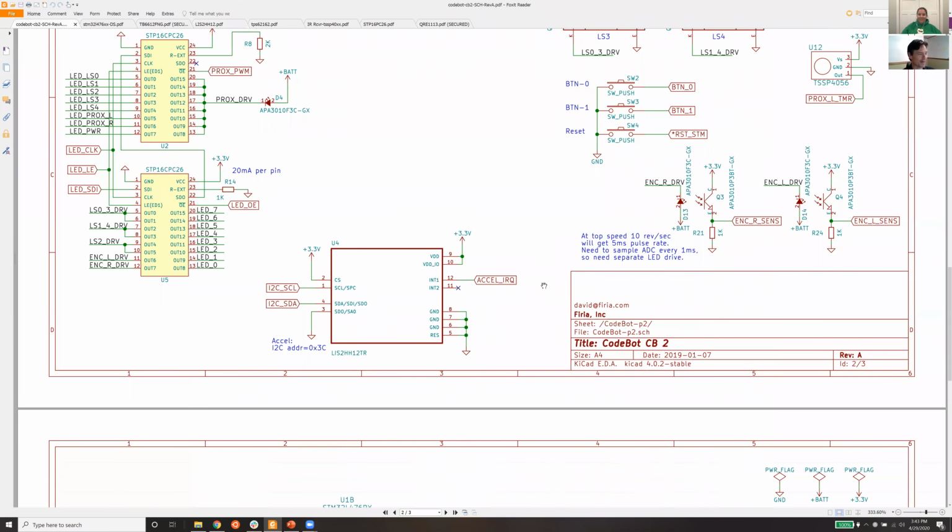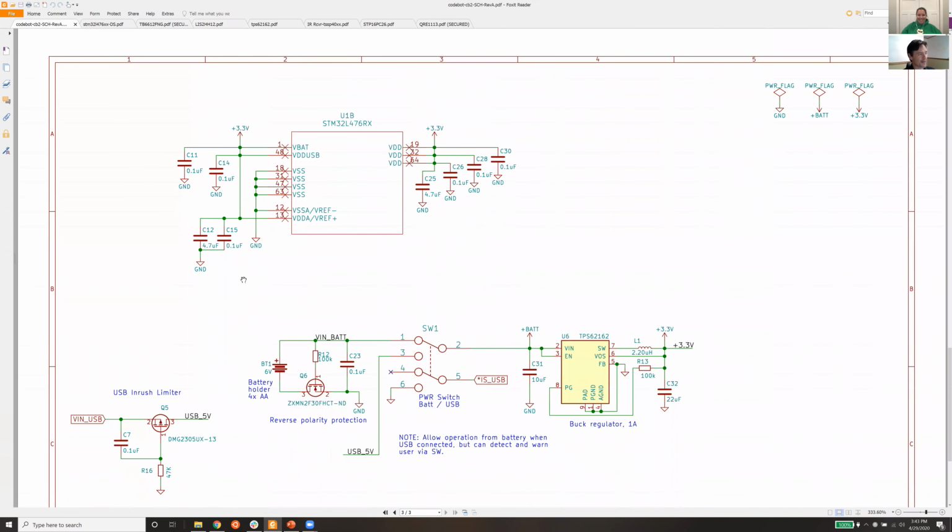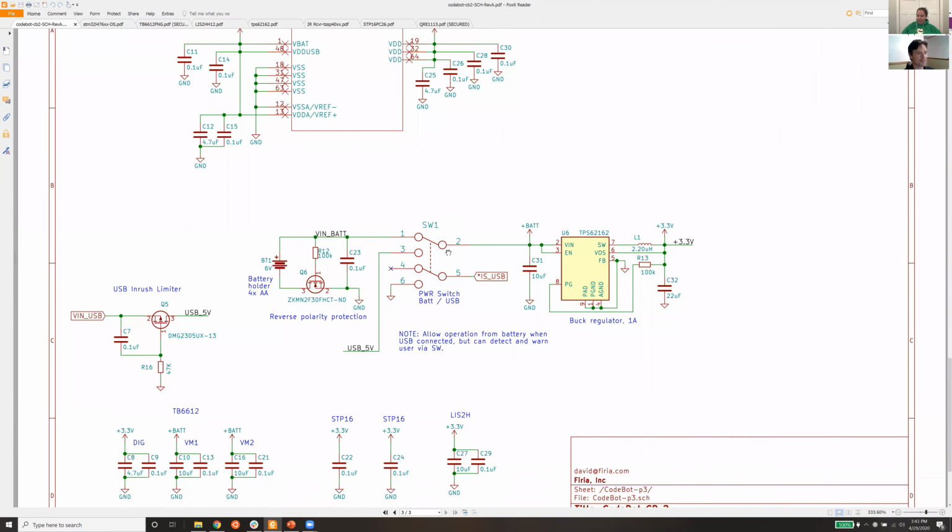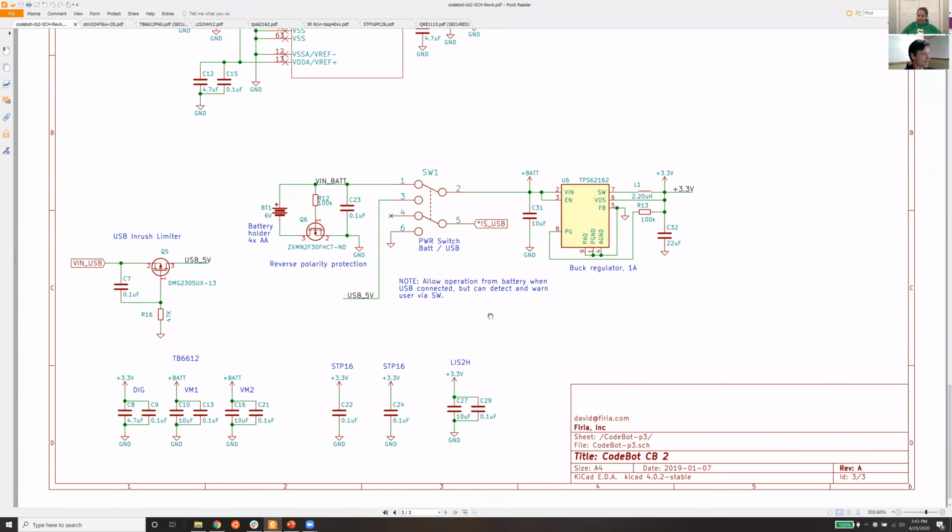We're almost through the schematic. Last page here, there's a power section of the STM32. So that's just where we hook power up to it. Nothing exciting there. And then the power supply is the last bit. I remember pointing out, hey, here's the little switching power supply, and there's that little chunky rectangular thing that's the inductor. That's actually the power storage element in combination with this capacitor here.